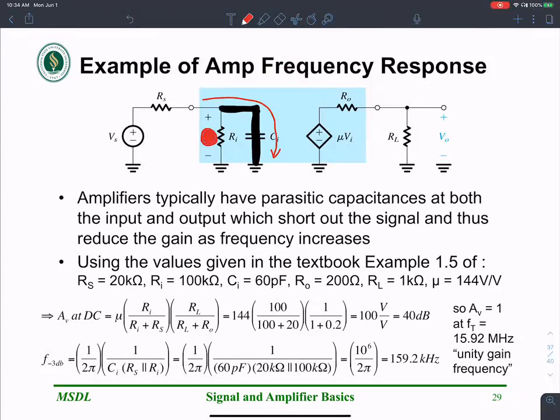When there is no voltage across this resistance, there is nothing to amplify. So the very idea of amplification is negated because of the short circuit of the capacitance. The capacitance at high frequencies provides a short circuit that bypasses the resistance. Therefore, the amplification is killed, and that reduces the gain at high frequencies.